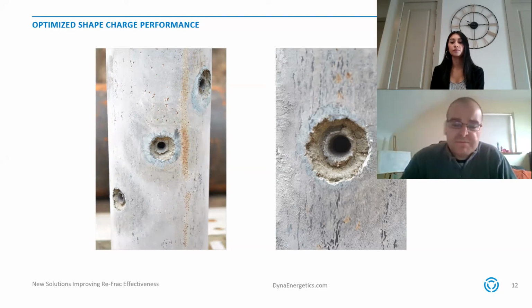This is a very good picture that shows the casing between the inner and the outer string, where we peeled back the outer string just to expose the casing layer, showing that there are absolutely no cracks or fractures between the individual perforating ducts. These cracks, as previously mentioned, would be very undesirable and would allow fracture pressure to find the path of least resistance and connect in the cement sheath for perforation hole-to-hole connection. This could and will reduce the effectiveness of fracture stimulation inside the formation. So maintaining this cement integrity and casing integrity is extremely important for Refrac operations.